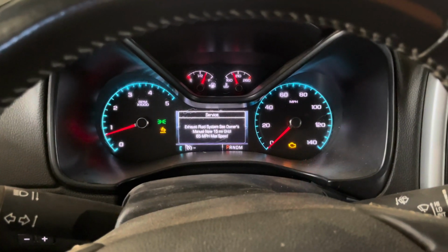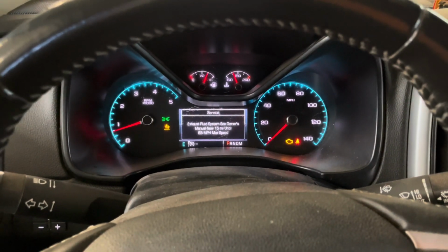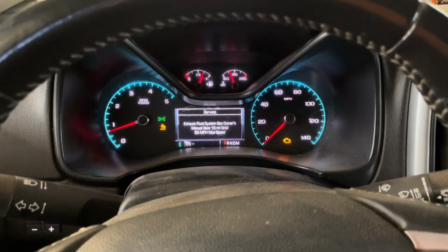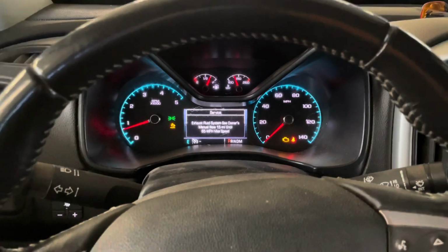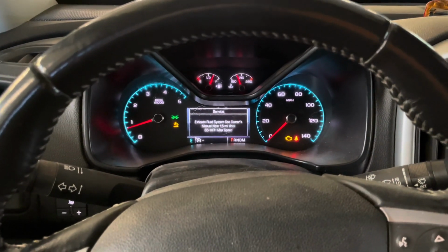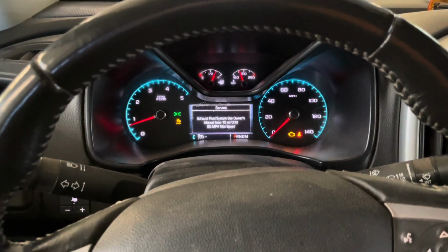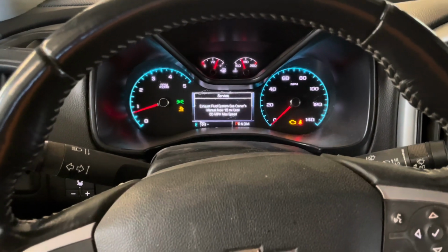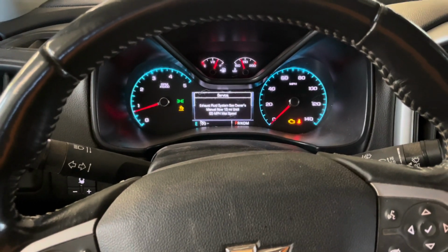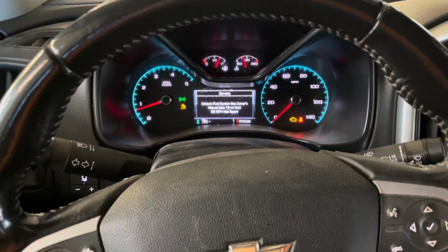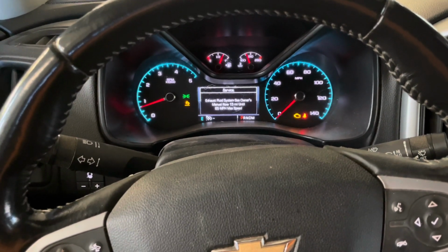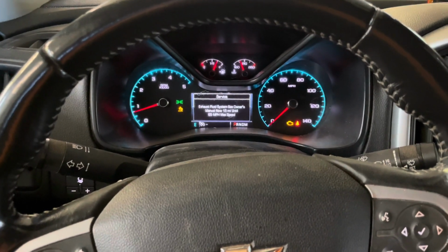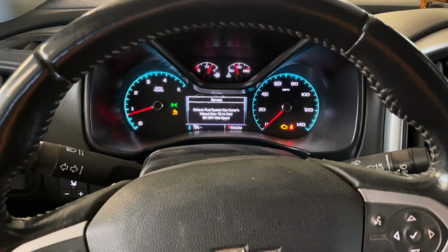Well, today I've got a 2016 Chevy Colorado 2.8 liter Duramax diesel exhaust fluid system. See owner's manual. The customer is upset because he's had another shop diagnose it and they told him that it needs a diesel particulate filter. The reason the customer's upset is because I just replaced the diesel particulate filter about 13,000 miles ago for a P2002 code. So, let's see if that other shop is correct in their diagnosis.